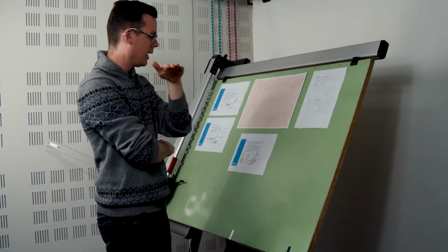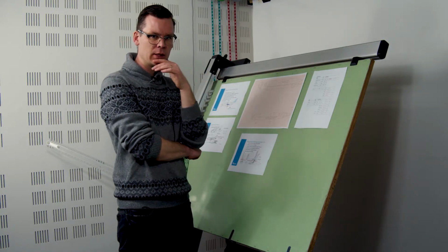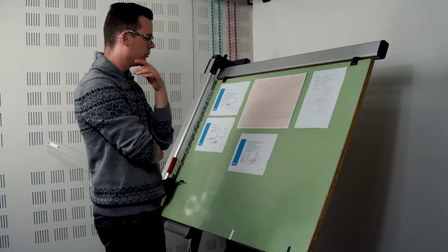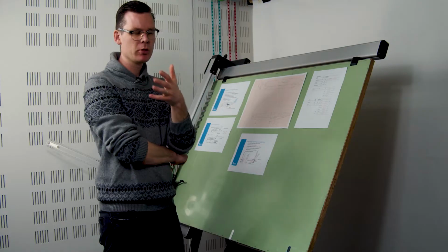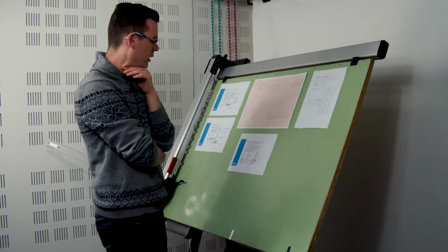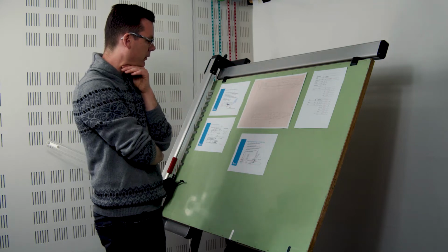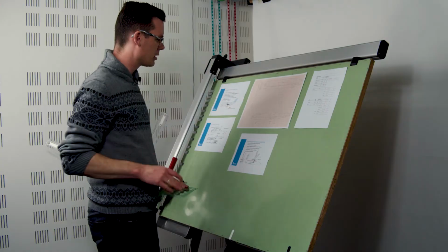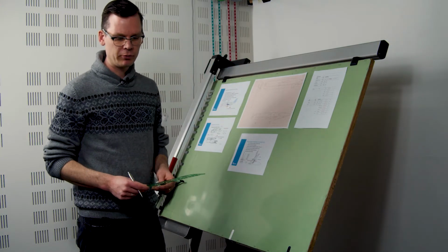Typically we do not want the deck angle to fall below 3 degrees, because then it becomes uncomfortable to walk inside the cabin when it's parked, but also for people to load the galleys, for example, with carts. So 3 degrees is really the minimum. I choose to have the airplane nice and level here to make things straightforward and easy.